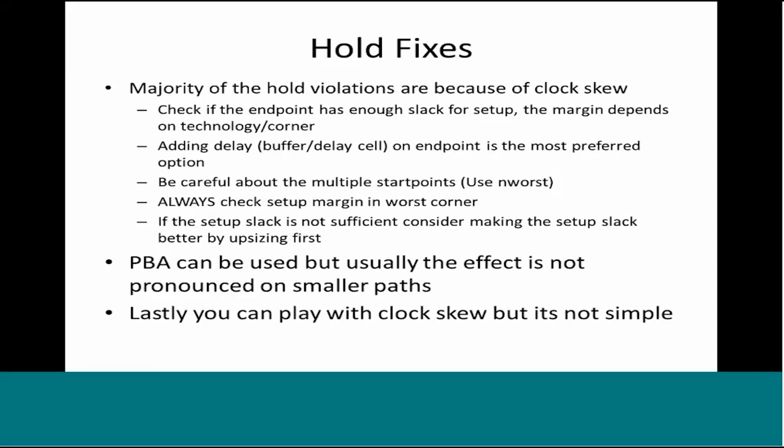So this is again the reason why in synthesis you don't worry about the hold timing, because you are not synthesizing for hold, you are synthesizing for performance, which is setup, and there is no clock tree, so there is no clock skew in place there, so there is no need to worry. And such hold violations are easiest to fix. Simply you have to add some kind of a delay element, which is either a buffer or a delay cell. Delay cell is just a kind of a buffer with more delay.